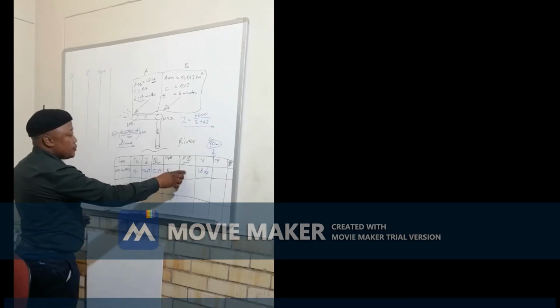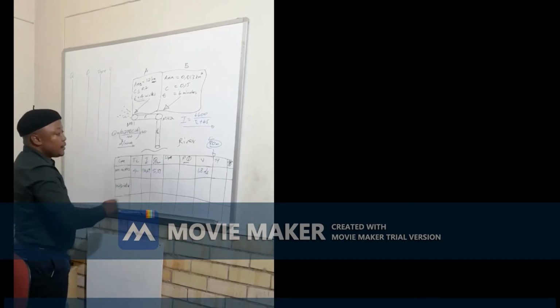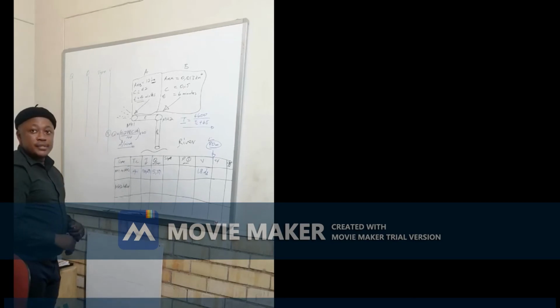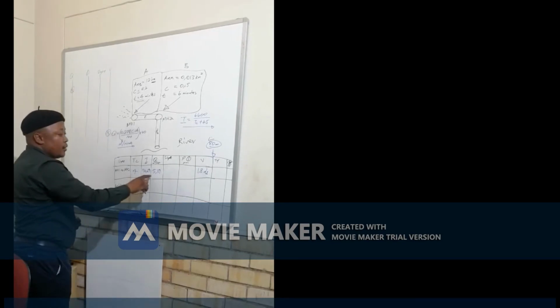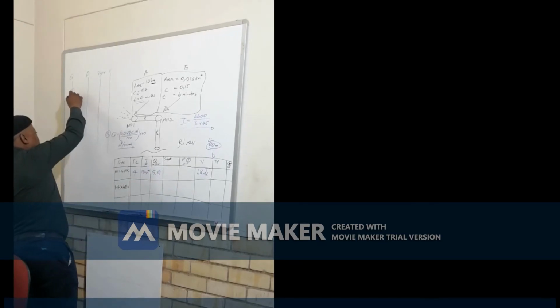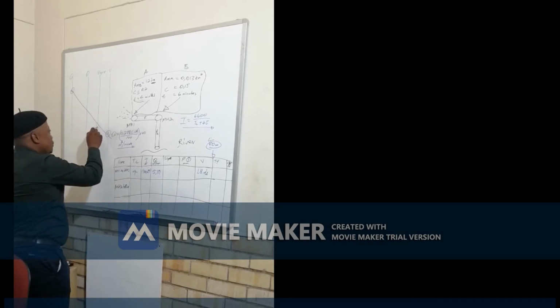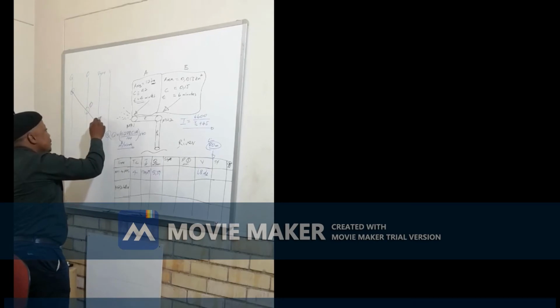Now according to the slope and the diameter, you simply go to the nomogram, you read your value of 1.8 and possibly the other value that you have of 5.39. Then you draw a straight line with your pencil, and then you read across what other values you might be getting for the diameter as well as for the slope.